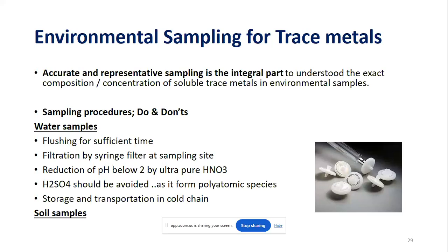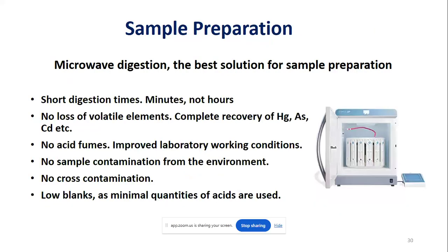For that, I need to initially flush 10 to 15 liters of water. During that time, the water which has remained stored for a longer time in the pipe, this metal pipe, will come out, and after that the actual groundwater sample will come out. So I need to flush the 10 to 15 liters first, and after that I need to collect the water, which could remain the representation of the sample of that particular borewell. So that is what I said, there are various protocols.